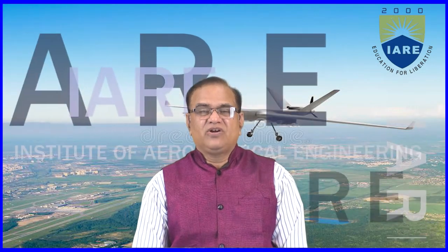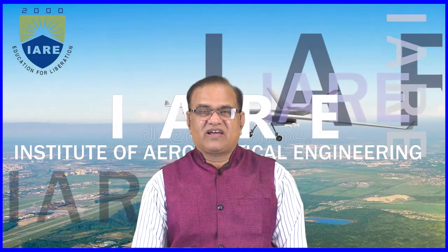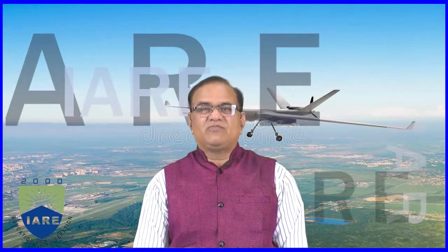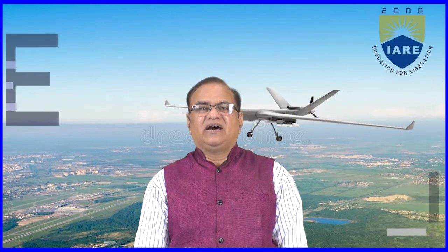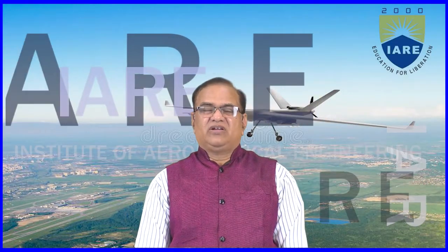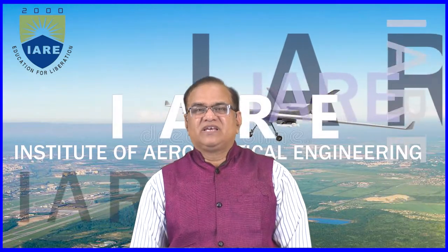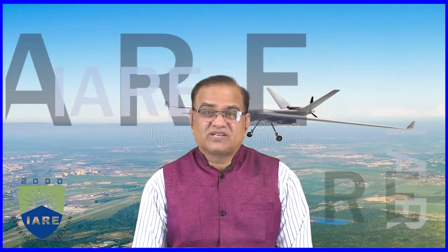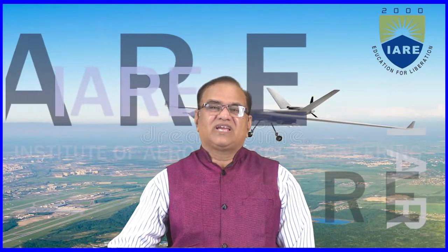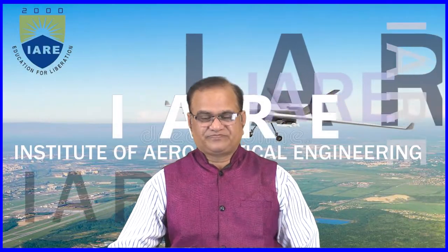If we are not able to make Cm0 sufficiently positive, then it is very difficult for the aircraft to trim at a positive angle of attack. If your aircraft is not able to trim at a positive angle of attack, then the controlling ability or the pilot response will be nowhere. So control will be ineffective. We want some effectiveness in the aircraft so that we can make the aircraft stable.